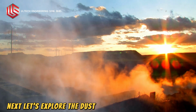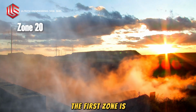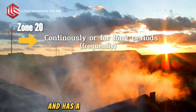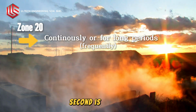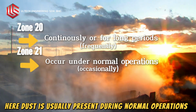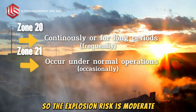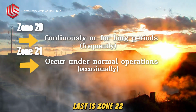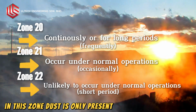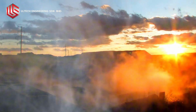Next, let's explore the dust zones for combustible dust. The first zone is Zone 20, where combustible dust is constantly present and has a high explosion risk. Second is Zone 21. Here, dust is usually present during normal operations, but only in certain conditions, so the explosion risk is moderate. Last is Zone 22. In this zone, dust is only present in abnormal situations, which means the explosion risk is low.